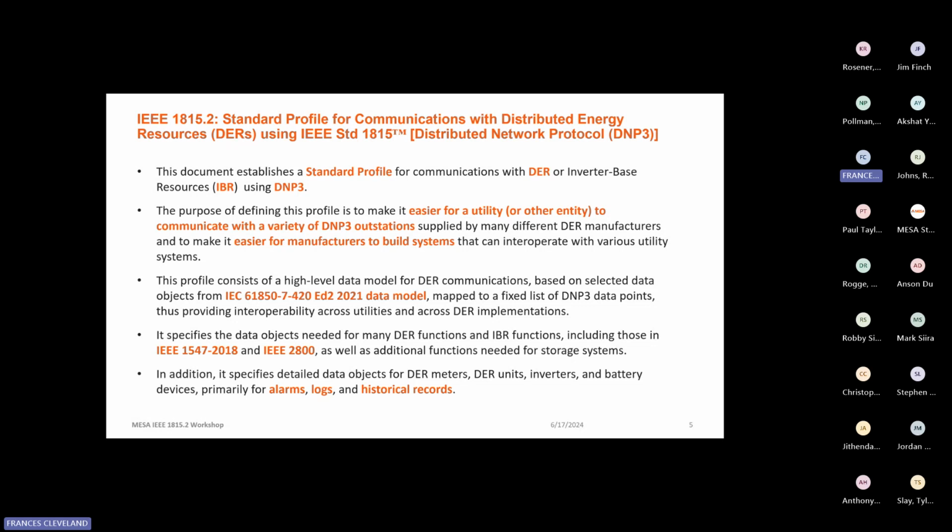So it establishes a standard profile for communications with DER or inverter-based resources, IBR. These are typically the larger systems using DNP3. So it is really critical to have such a standard, both for utilities as well as the manufacturers and integrators.